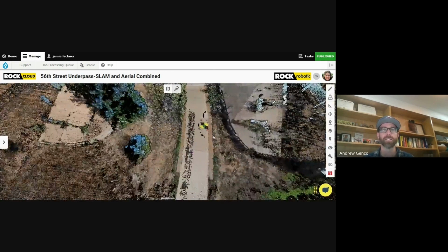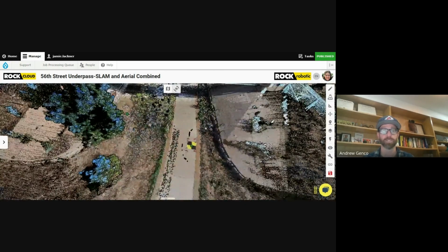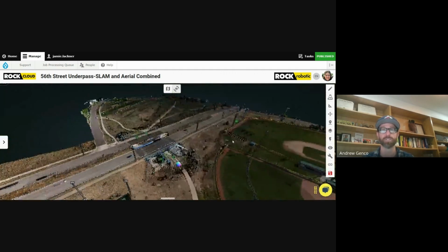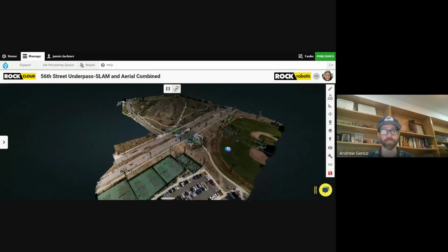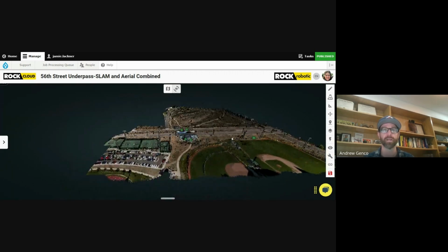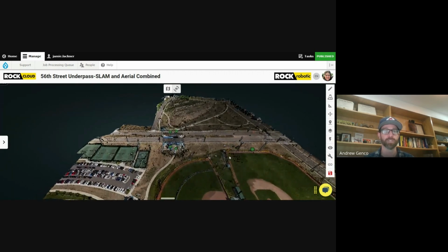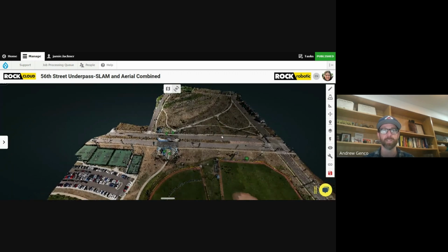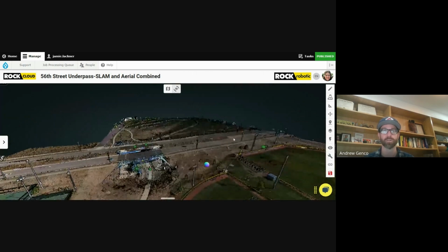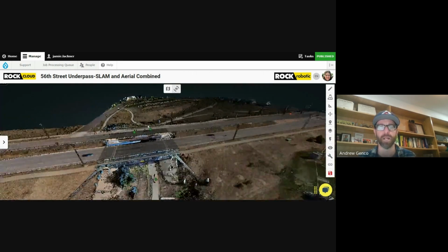And then also any safety or airspace restrictions. It is the pilot's responsibility in the United States to ensure that they know of any flight restrictions, airspace restrictions, or altitude restrictions for their survey area. And then also understanding what sort of safety parameters might be in place, whether it's utility lines nearby, people being on site, and so on and so forth. And those can be made when you're arriving on site.